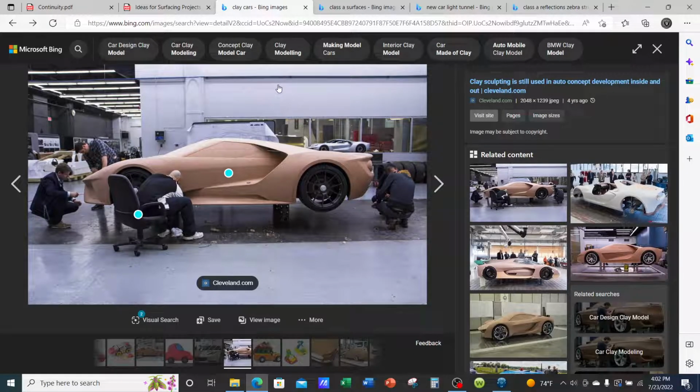They're the ones that take those digitized surfaces, or point clouds, of the clay model and turn them into manufacturable surfaces. So if you're a digital stylist, we need to recreate these surfaces. The reason you have to recreate them is that since it's clay, there are going to be some small imperfections or even holes. So you need to recreate the surface to then model the part and also create clean surfaces for manufacturing to make the part.